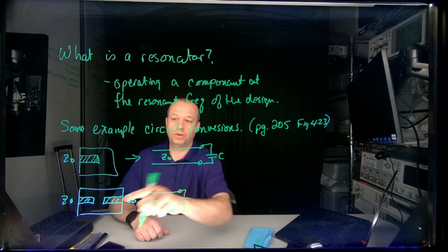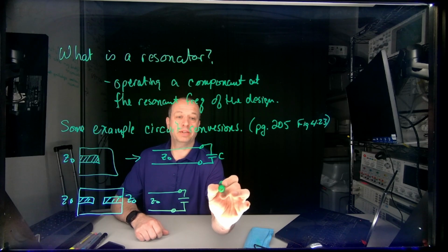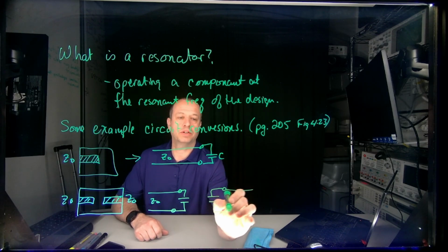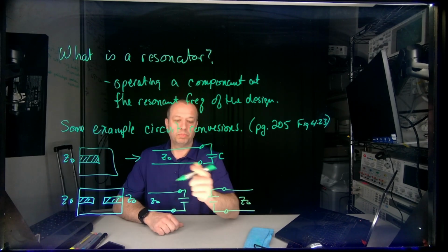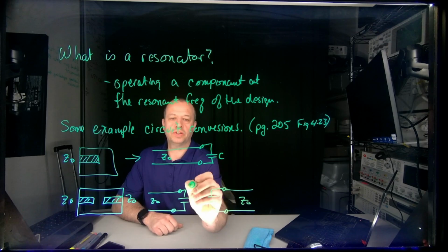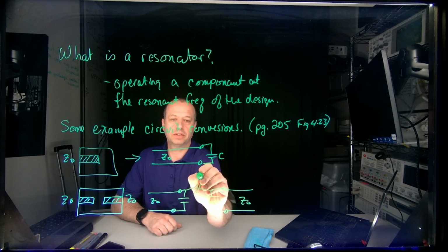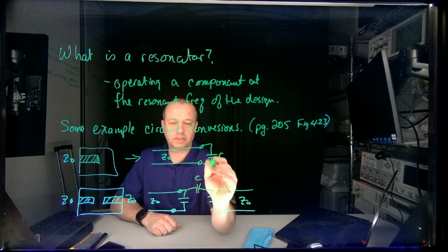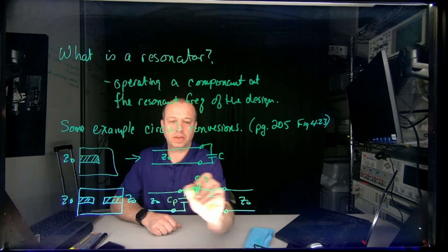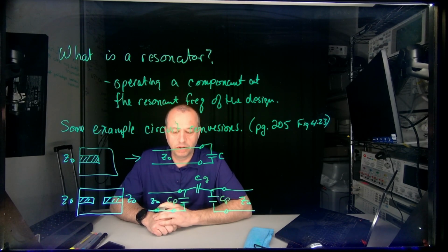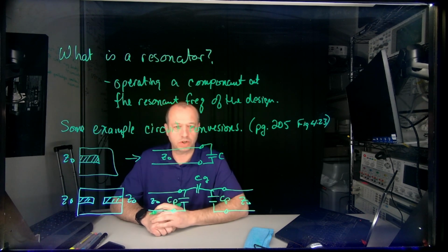Let's just do each of these independently, and you will see that both of these have capacitors attached to them, both with some characteristic impedance. But then, because these two are right next to each other, they have their own coupled capacitance. So this is CG and CP and CP. So we have three different capacitors by these two traces.